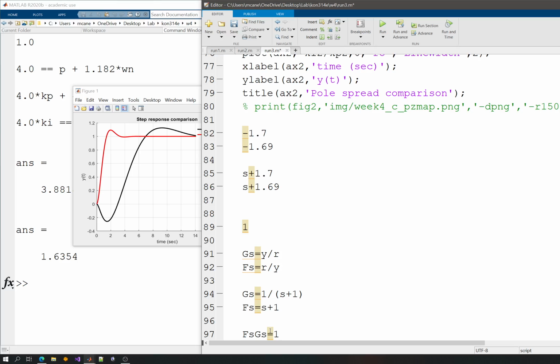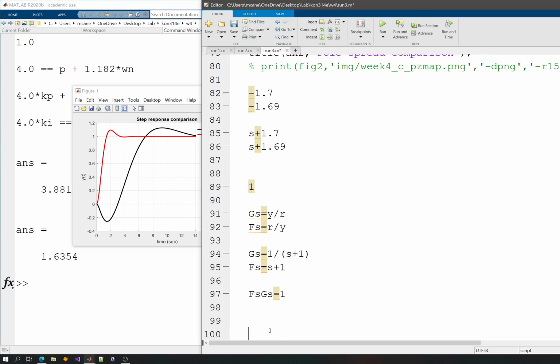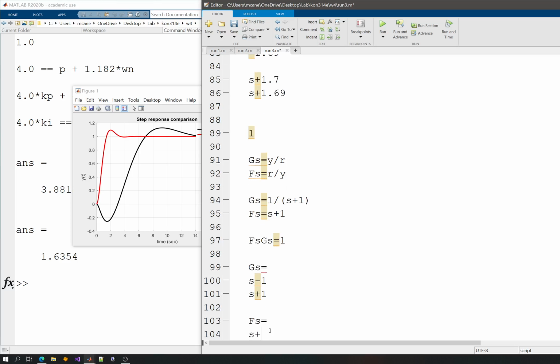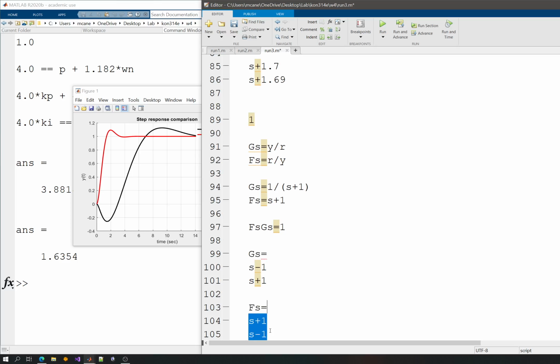on the left-hand side. This was not the case for our closed loop control strategy. If not, I have some issues because the inverse will be on the right-hand side. Let's say we have s minus 1 divided by s plus 1 as a system transfer function, G(s) equal to this. The inverse for the controller will be s plus 1 divided by s minus 1. So this isn't a stable controller, and this will cause internal stability problems.